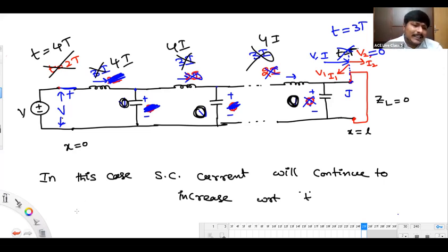What is the aim of transient analysis? Anybody? What is the aim of doing this transient analysis? Just to find out the over voltages, right? How much maximum over voltage the system is going to experience, we have to know, based on which we will be selecting the insulation level of the system.